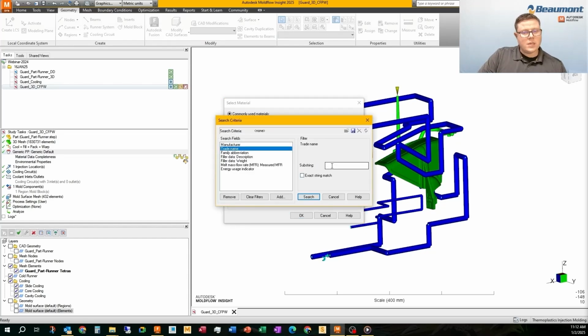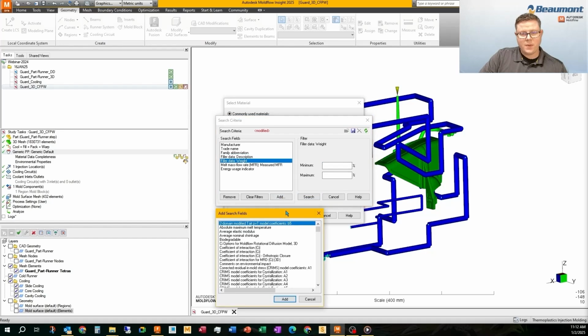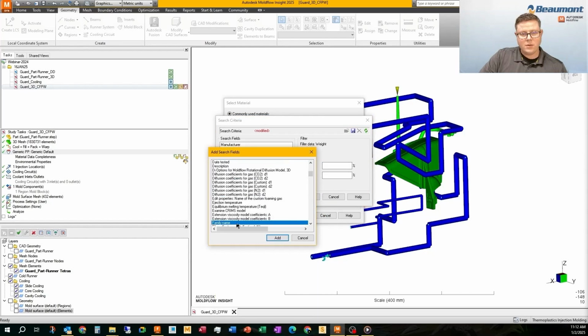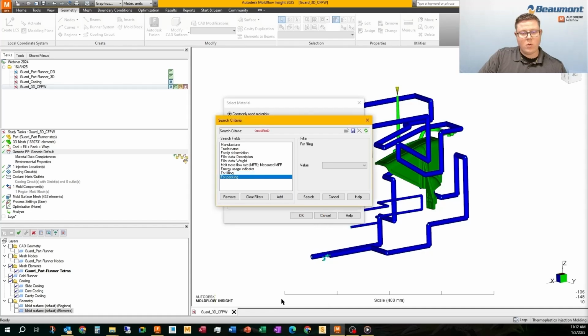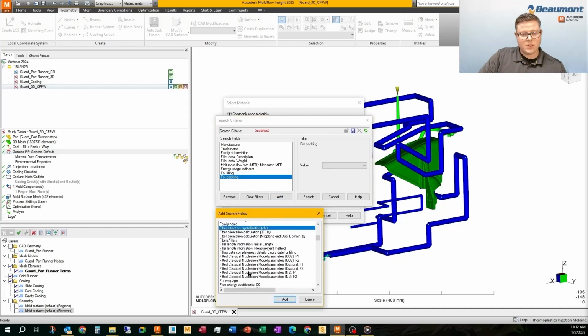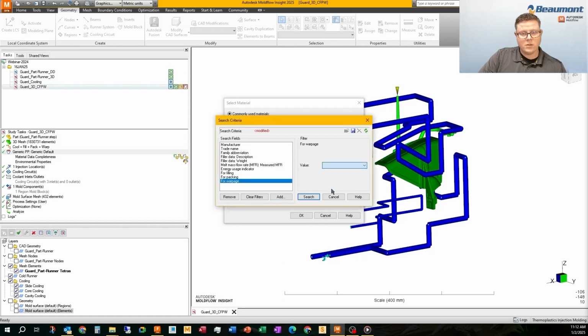And what I'm doing here is I'm starting to select a material. Some other features we're allowed to search by are filler, filler weight, description. But you can add any feature that is inside of a UDB file, any type of location. And I'm adding the quality criteria for the Moldflow tested materials. So I'm adding filling, packing, and warpage, and I'm changing them to the gold rated properties.